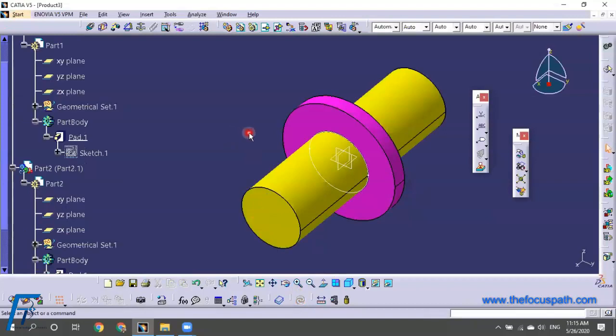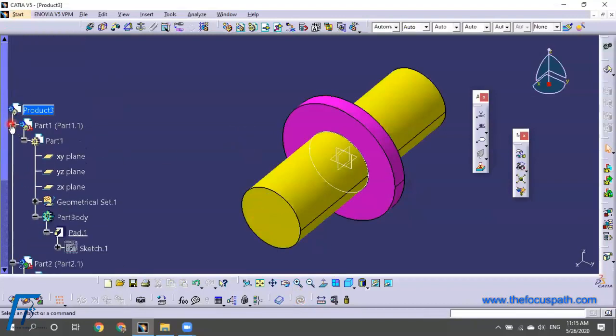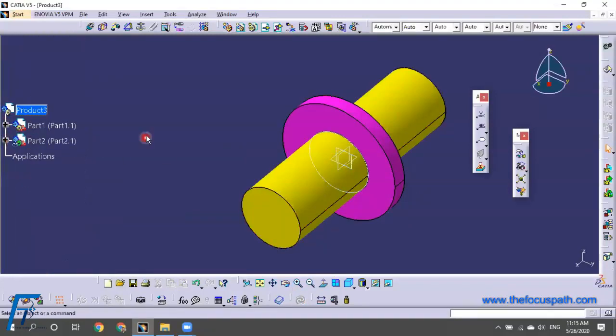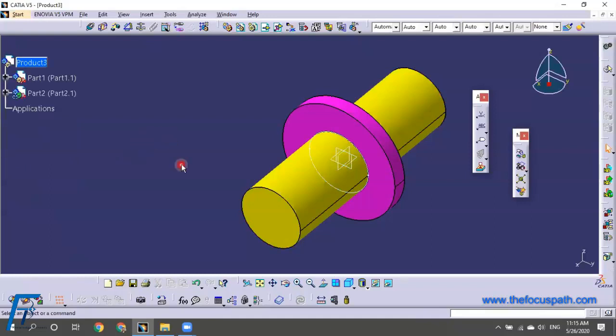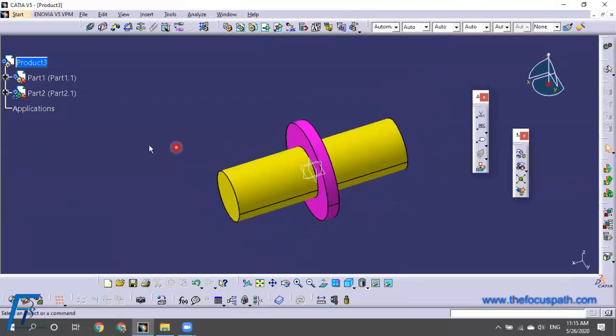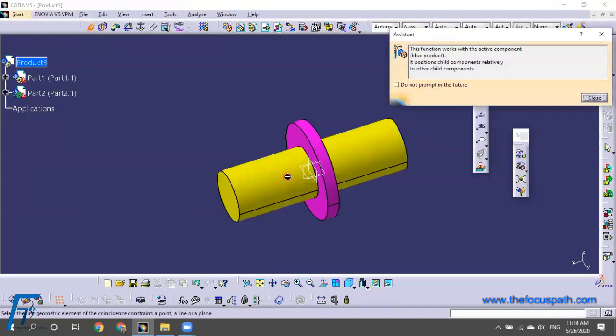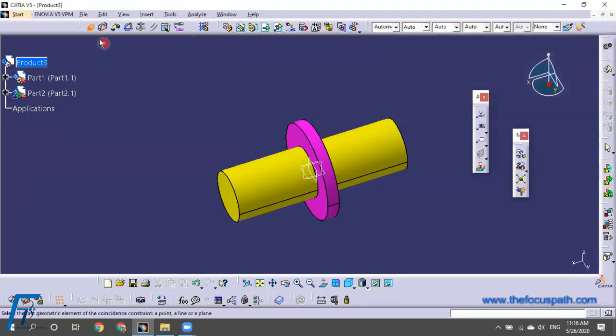You get it. So that means when you see that contextually referred, when we say that this component is contextually referred using external reference, you can see a blue gear with a green gear with a chain drive indicating that this is contextually linked. And most of the people make a similar mistake. Once it is done, you try to give constraints. Already this is constrained. It is not required for any constraints, right? So why give those constraints?